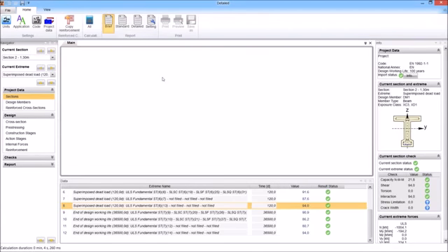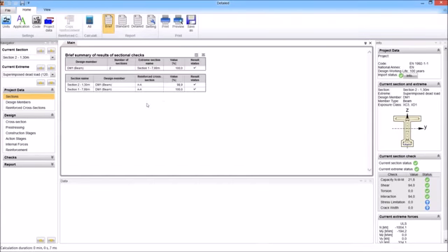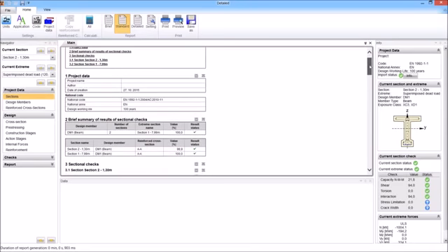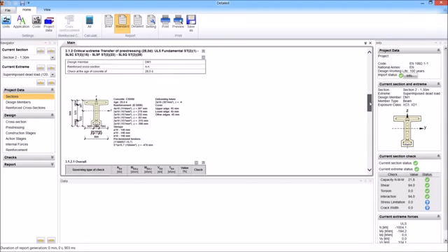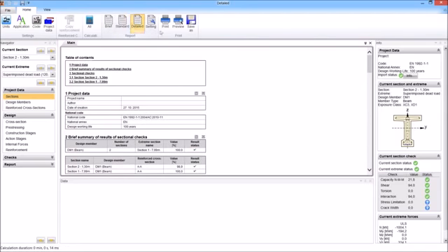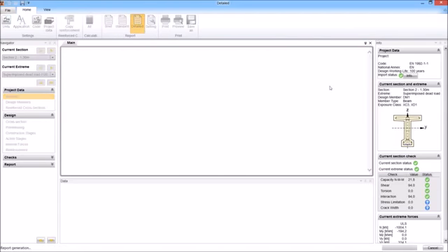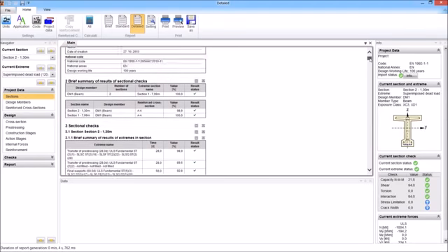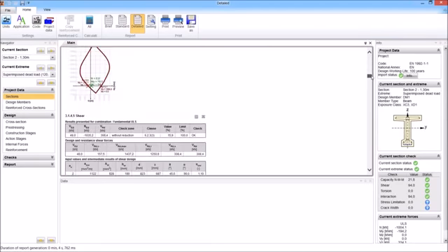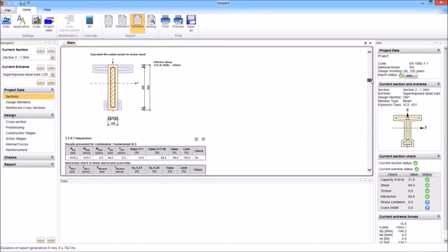We can see a brief report, each section only one row. Standard report, usually in pre-stressed concrete it is a little bit more than one page, in non-pre-stressed it is one page. Or detailed, which generates all the pictures and all data, tables, intermediate results. You can see the reinforcement, interaction diagram, torsion.